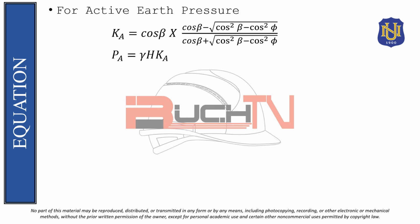Then we will get the active earth pressure, which is equivalent to gamma times H times the active earth pressure coefficient K sub A. Then we can get the active earth force coming from the diagram, which is just the area of the triangle, which is 1/2 the active earth pressure times H, or simply 1/2 gamma H squared Ka.